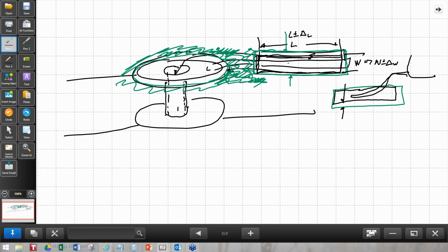However, there are some things to know about vias and solder mask. Sometimes people want to insulate. Well, solder mask is not a reliable insulator. In other words, you can't guarantee that it will actually support a high voltage.